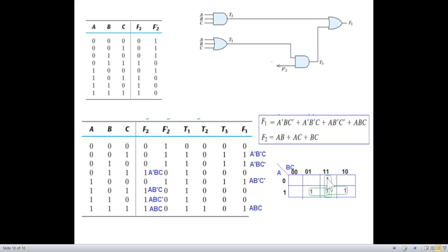So there's a 1 here. Similarly, this one, this one, this one. I hope you have learned by now how to plot on the K-map. And now we'll group them to minimize. So these two can be grouped, and you can see A is 1 throughout this, and here only C is 1, so AC. So we get this term. The second term is also A, and then we have B. So AB. And the third term is BC. So from here, we get this answer.